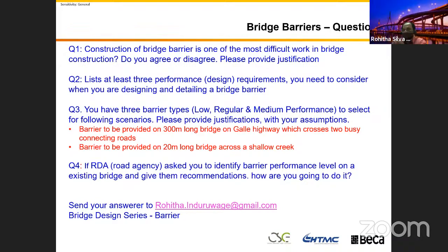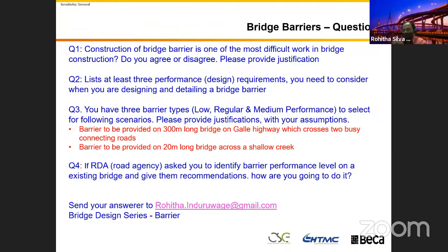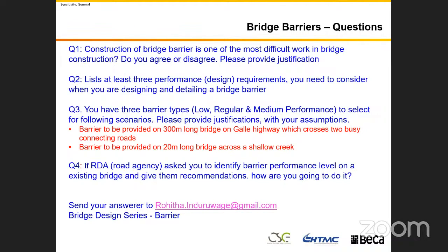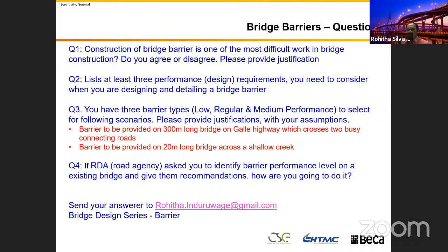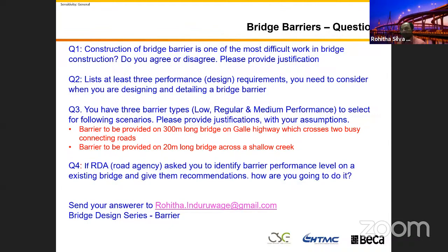Is that ULS or working load for those piles? ULS, also ULS. Okay. And also in those piles, the one over the water, do you remember the depth of the piles? The length of the pile is about 65 meters. And the depth in the water? The depth in the water at that place is about 17 meters, but in Bangkok, we got about